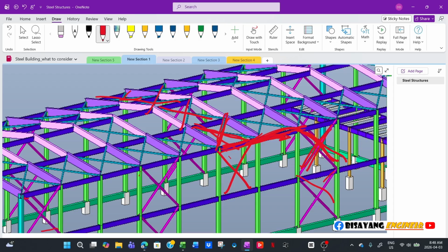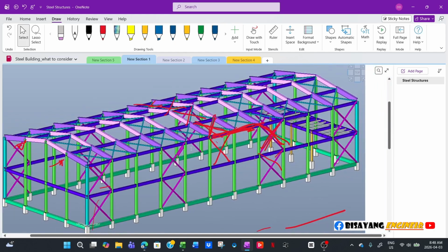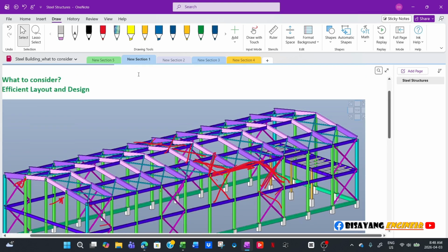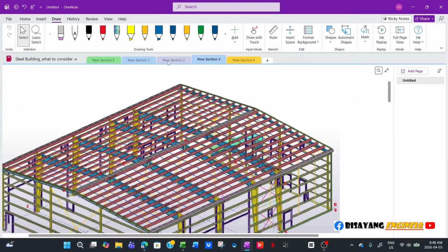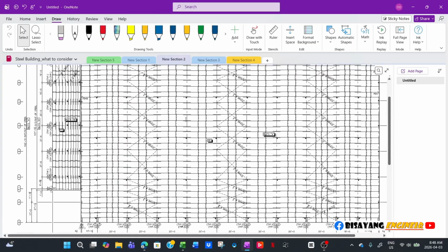So that's another thing. And then another consideration would be, instead of using a strut, I would say on all the metal buildings that I designed the foundation for, like 99% don't have a separate strut. They will use the girts and the purlins to transfer the load. So this one here, for example, on this particular building,